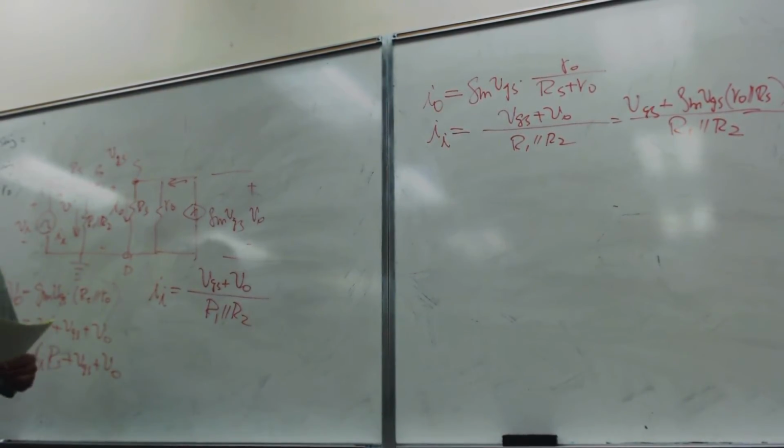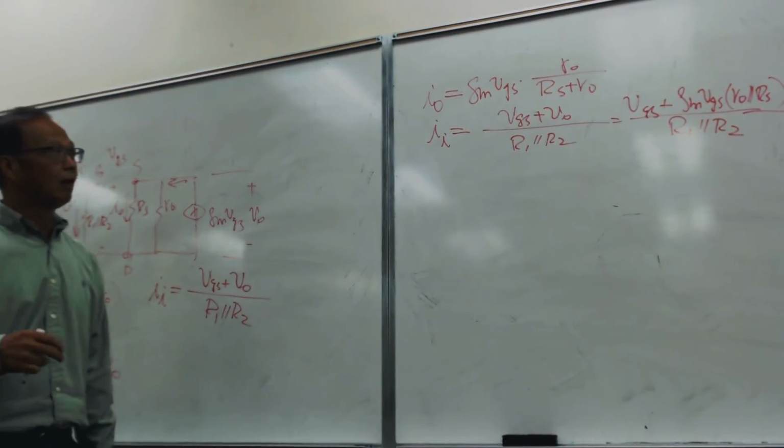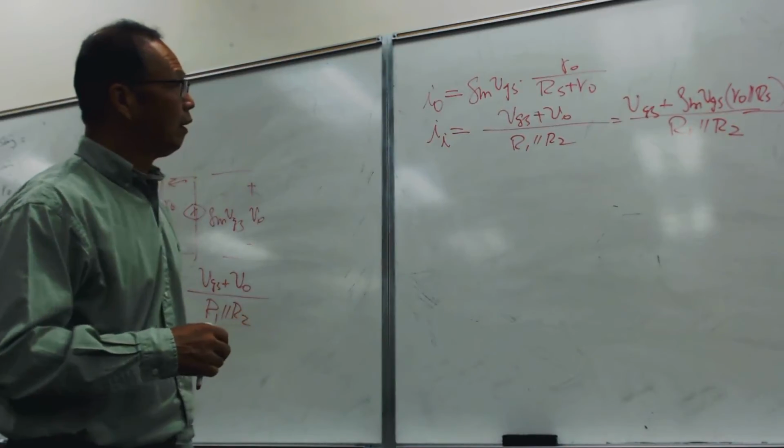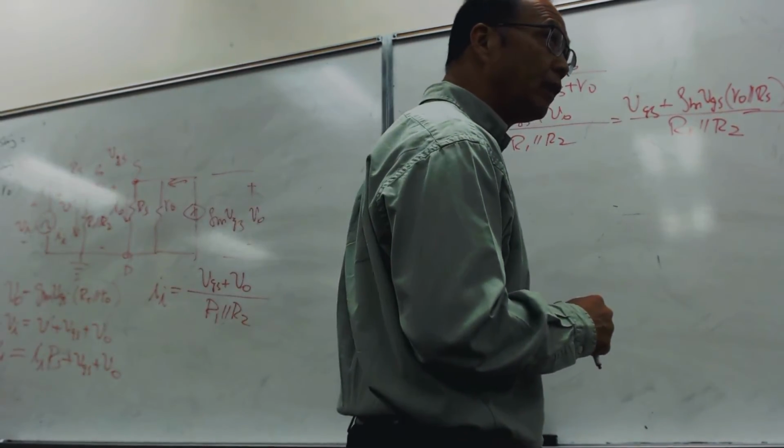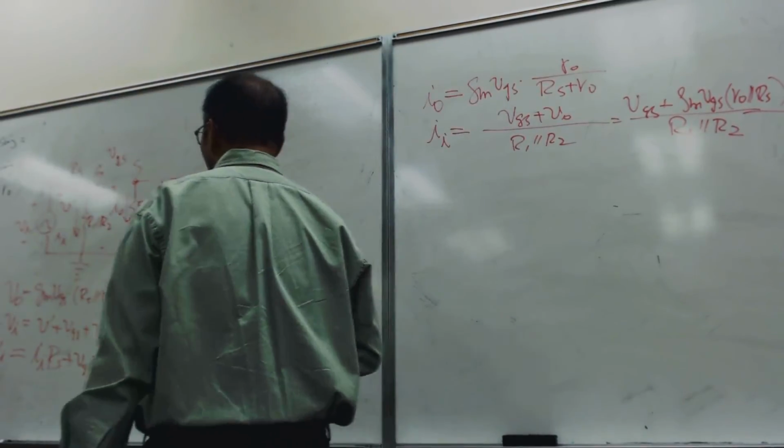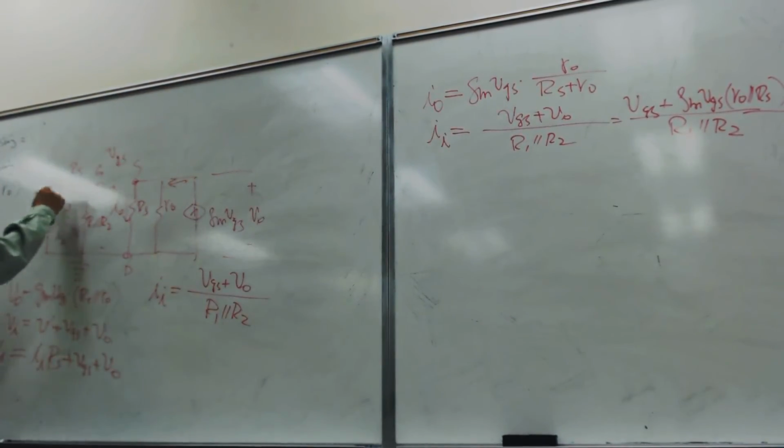So the input resistance, would that just be R1 parallel R2 plus R sub S? Oh, the input resistance? The input resistance now will be that plus that. Yeah, that's it.